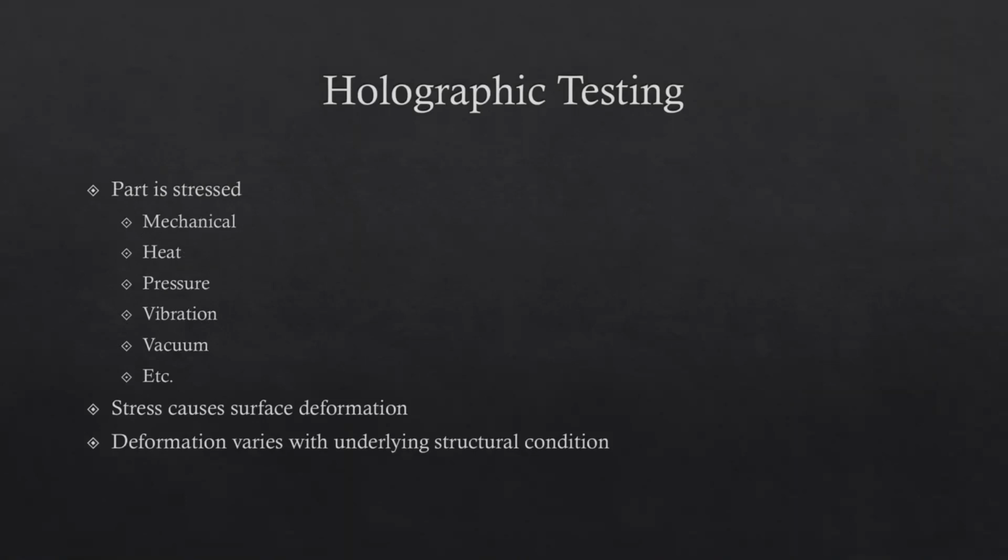So when I talk about stressing it, this is very similar. You'll see a lot of these are similar to some of the play with infrared, with thermography, where we had the excitation techniques. That's one way we can do it. So a part can be stressed. It can be mechanically stressed. And a very common way to mechanically stress something like the fuselage. Anyone have an idea how we might mechanically stress a fuselage of an airplane with everything that's built into the airplane? Yeah. By pressurizing it.